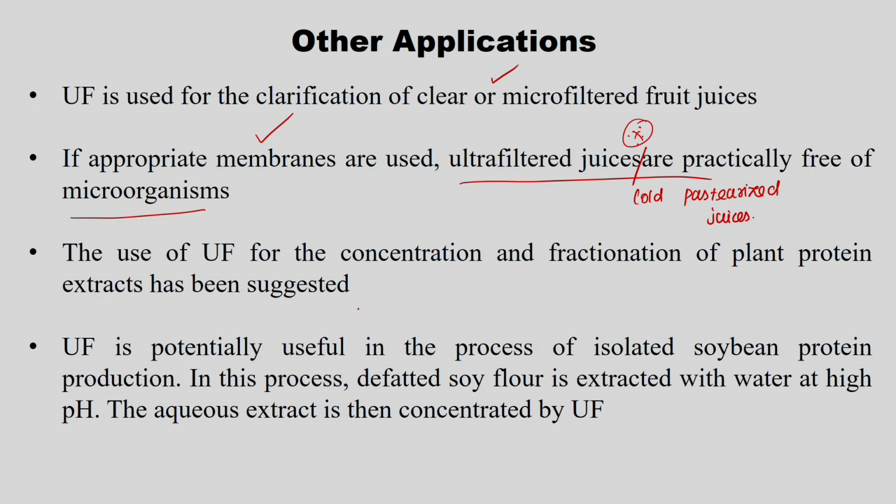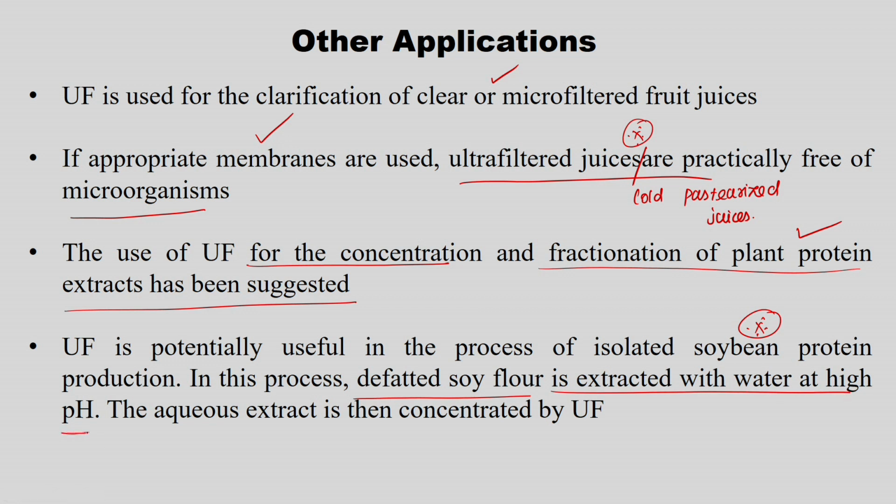The use of ultrafiltration for the concentration as well as fractionation of plant protein extracts is also suggested. So, that is nothing but plant protein concentration as well as fractionation. Ultrafiltration is potentially useful in the process of isolated soya bean protein production. So, this is another important application of ultrafiltration. In this process, defatted soy flour is extracted with water at high pH. The aqueous extract is then concentrated by ultrafiltration.